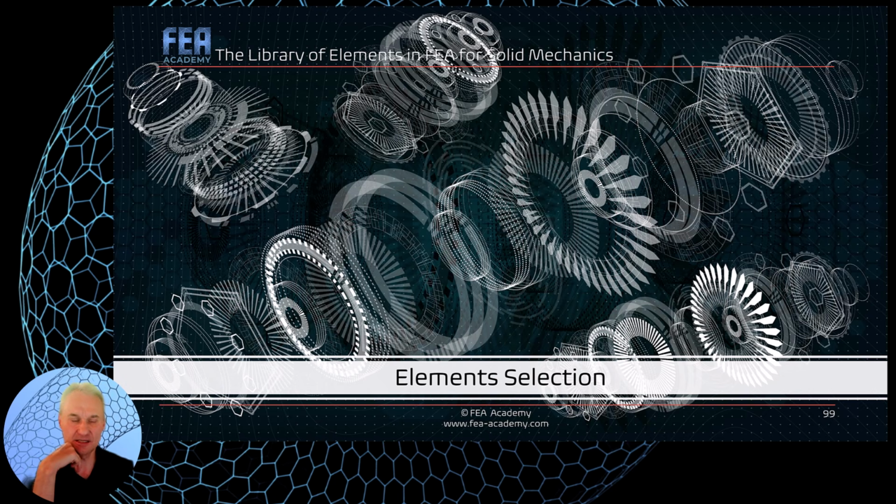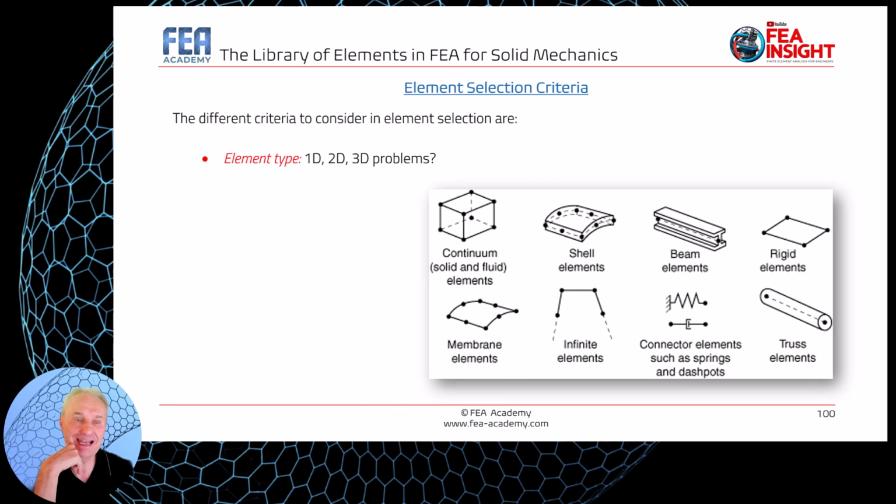Now let's discuss a little bit about the element selection. There are different criteria to consider in element selection. First, the element type. Selecting the element type is one of the most basic decisions you will make as an FEA analyst. Each element available in the library is associated with a family, and each family contains specific building blocks having the 1D, 2D, or 3D topologies.